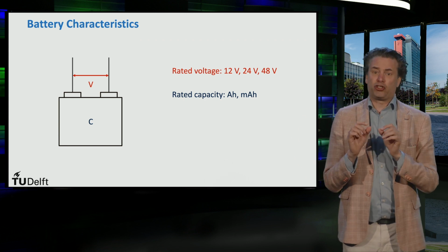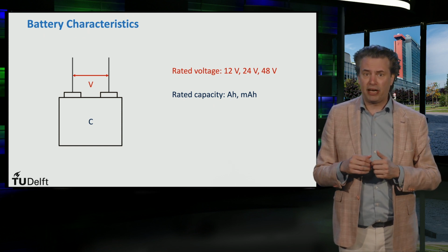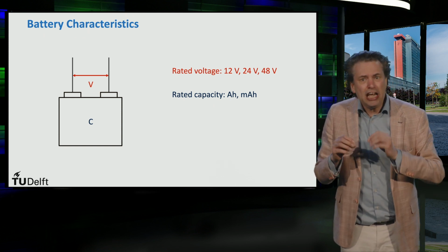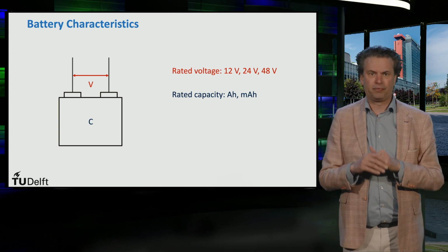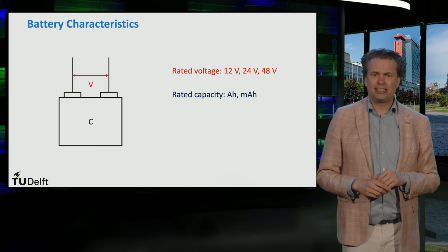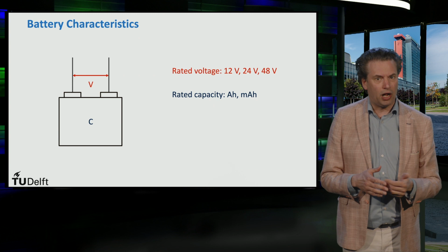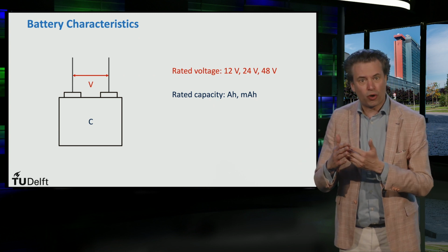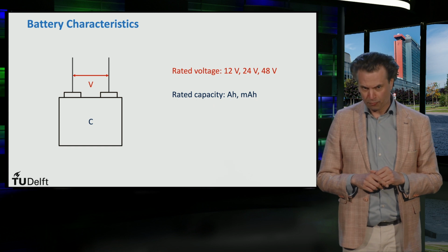This explains why a small cell has a lower capacity than a large cell that is based on the same chemistry, even though the open circuit voltage across the cell will be the same for both. From this we can understand that the voltage of the cell is more chemistry based, while the capacity is based more on the quantity of the active materials used.